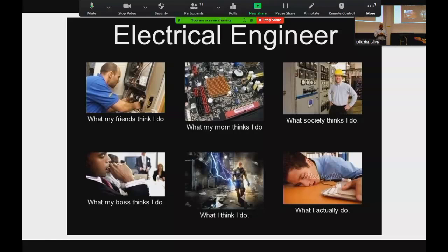I'll give my feedback as well. Fuses are fast. Circuit breakers tend to be mechanical and slow. So I used to run a class where we would blow up fuses and measure them on a scope versus circuit breakers, and circuit breakers will take 100 to 500 milliseconds, whereas a fuse is milliseconds. So what do you want to be connected to when you're being electrocuted?